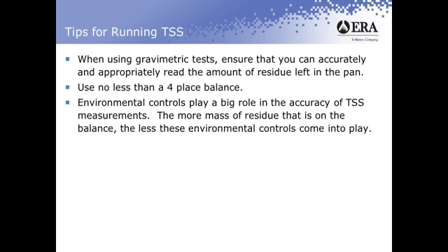So again, by using more sample and increasing the amount of mass that's on your balance, the less the moisture in your test is going to play a role. And we'll talk a little bit about that when we talk about blanks. So again, environmental controls will play a big role in the accuracy of your TSS measurements. I can't stress enough that the more mass of residue that is on your balance, the less those environmental controls will come into play.